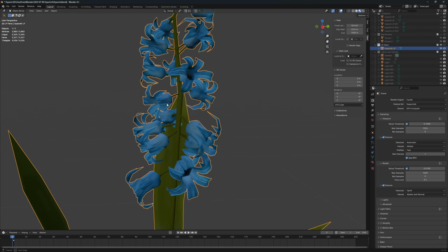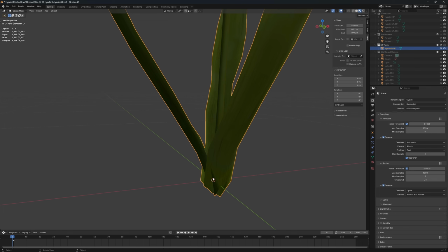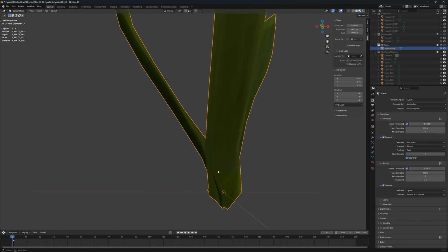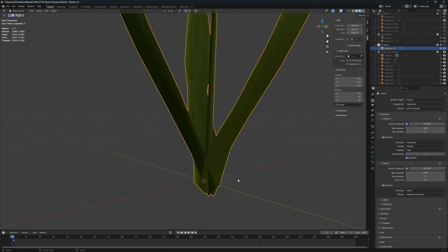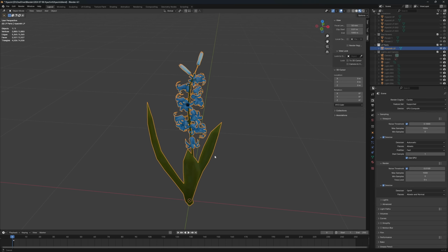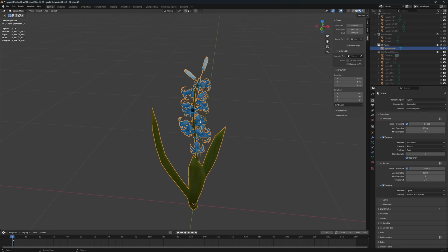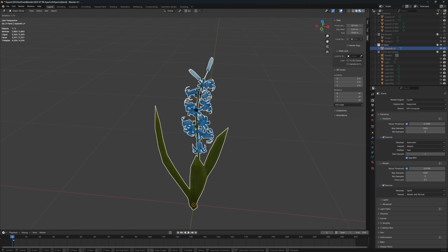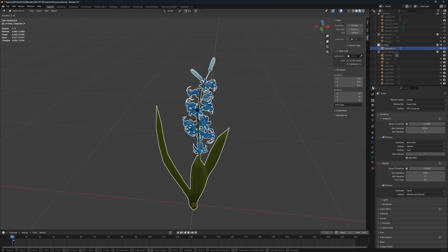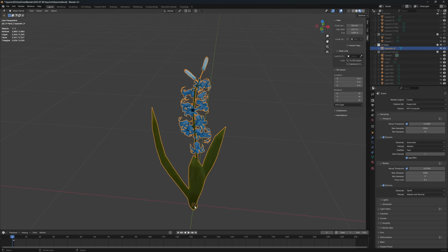So that's basically it. After the assembly, you had one low poly model, everything merged. The other thing I did was I put the origin point of the model down here. It's a bit lower than the actual ground plane. That's important because if you import it later onto a game engine, you are rotating and moving it based on that origin point. So it better be there.